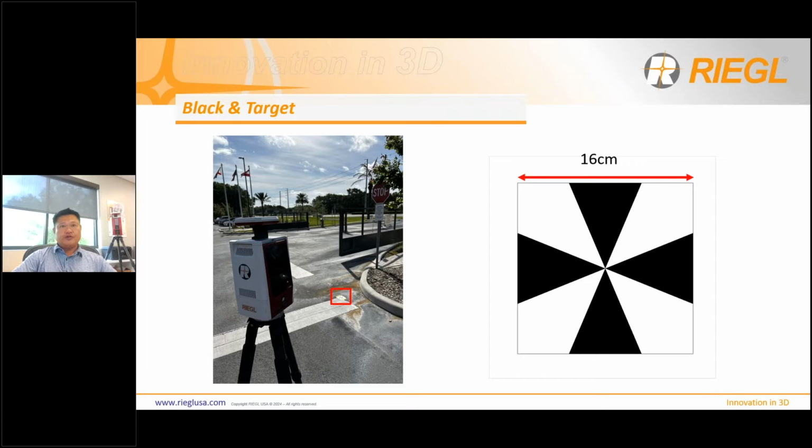And now you can put this on the back of a board. In our office we have controls set around the office with just a nail and a dimple, and I simply put the center right over the dimple and tape it, put a scanner next to it, and scan it. This can go, as advertised, preferably on the wall, so you get a good angle of incidence versus on the ground.